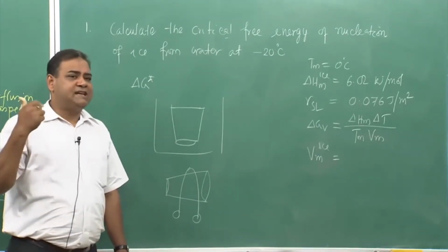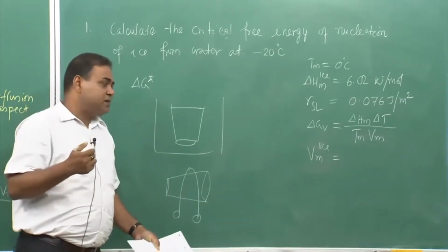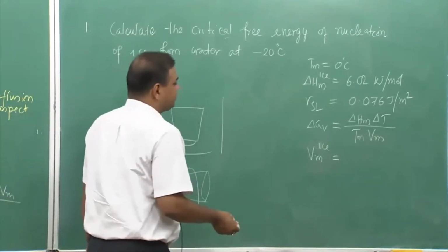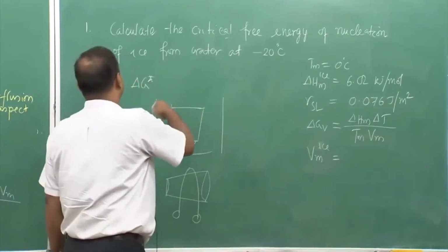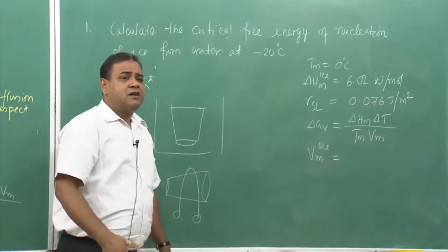When we talk about steel heat treatment, it might come across, okay, the Clausius-Clapeyron effect. So, right now we are not considering it, because our basic assumption while coming to this value was that the liquid to solid transformation does not have any volume change.